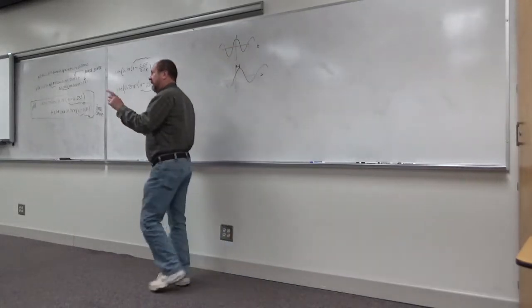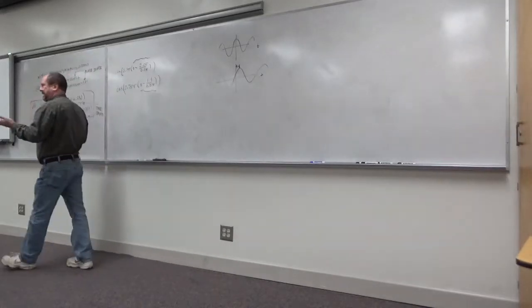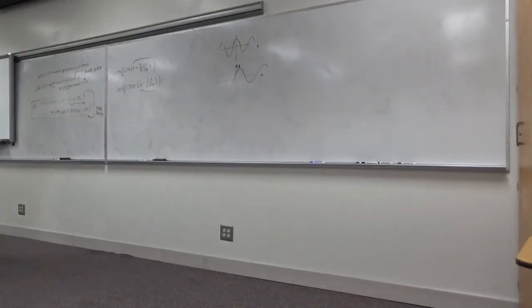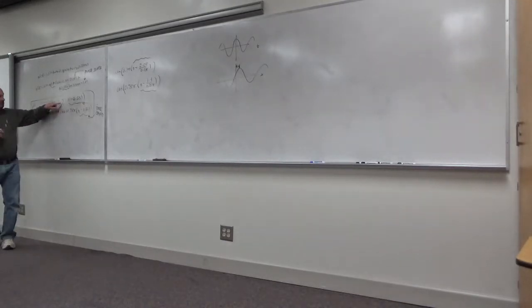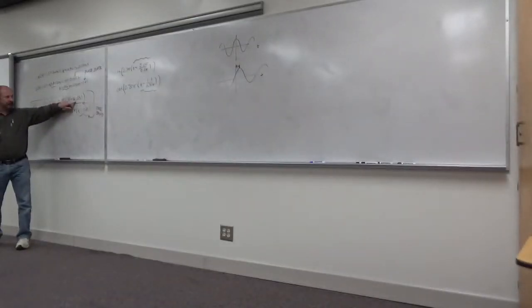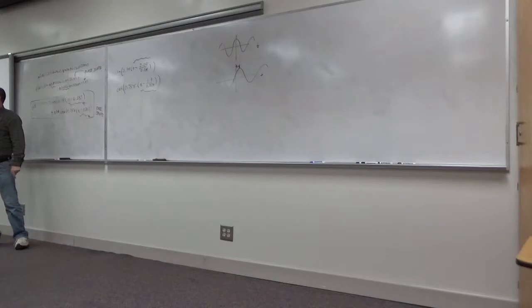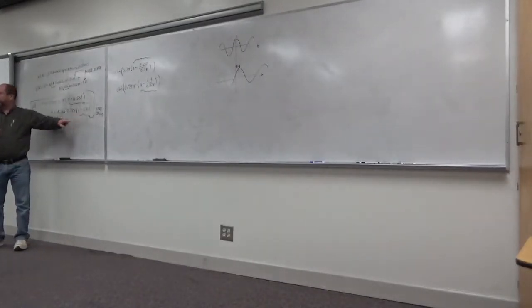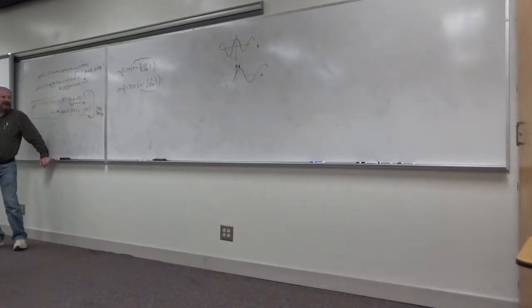Okay, now, what does it all mean? Here's what it means, and this is why the phase response is important. Look at this. This particular sinusoid got shifted by 6.5 samples. What about this one? It got shifted by less than 1 sample. That's a problem.